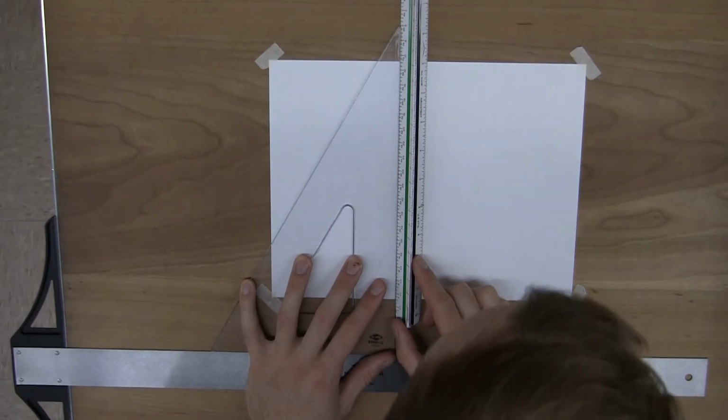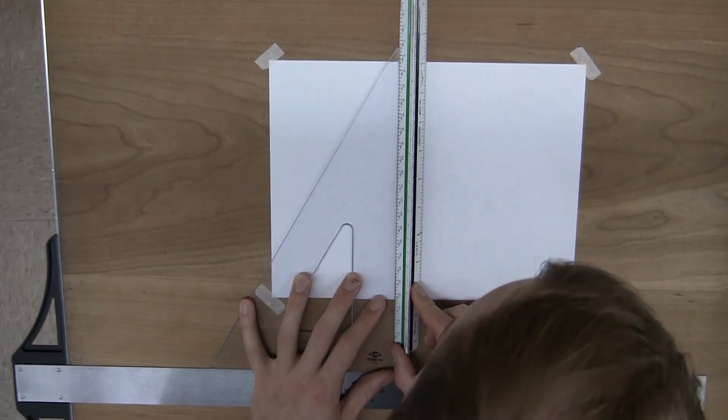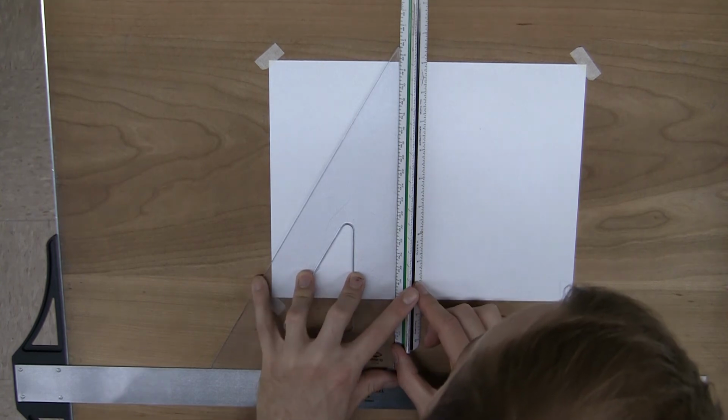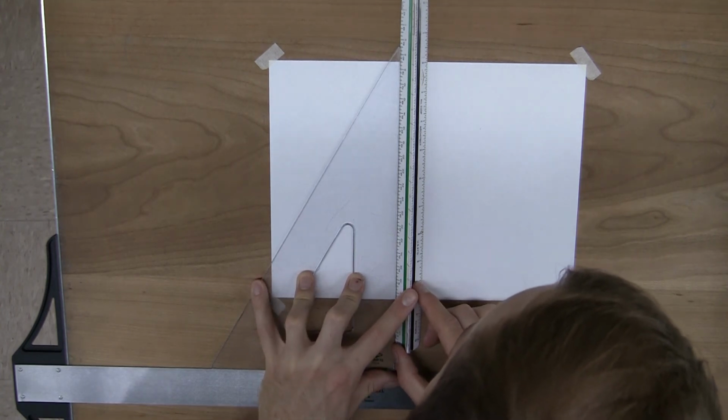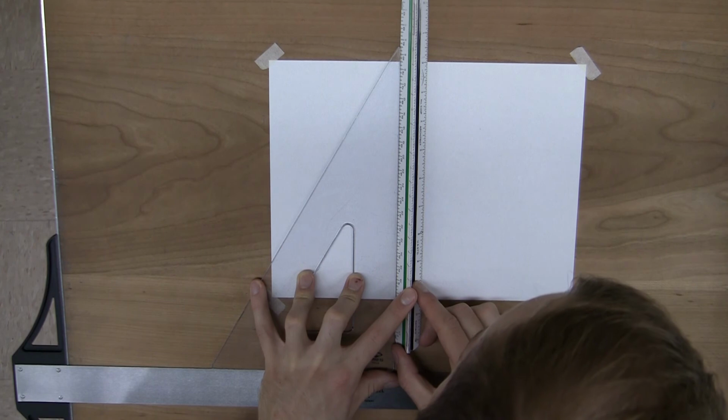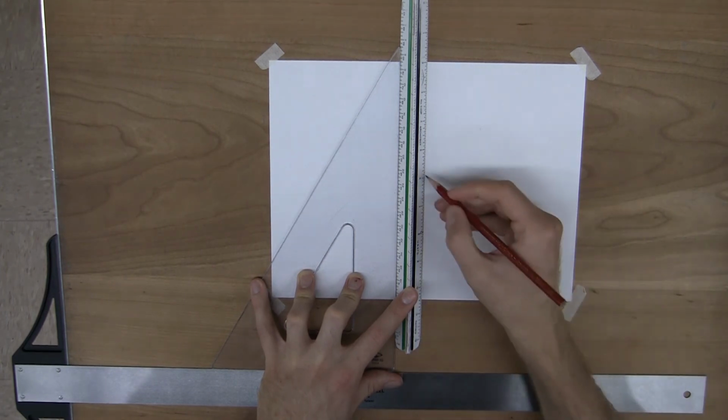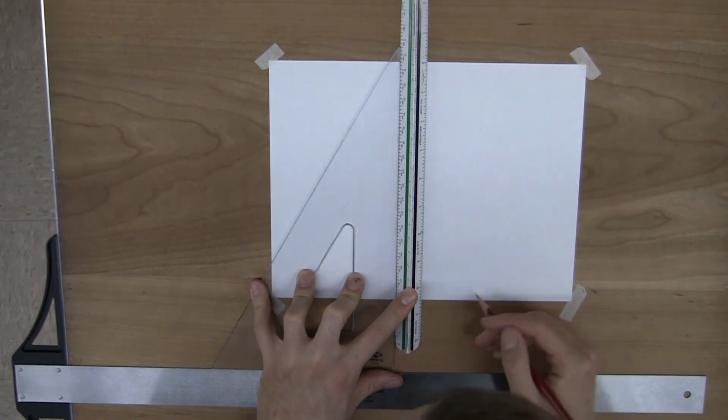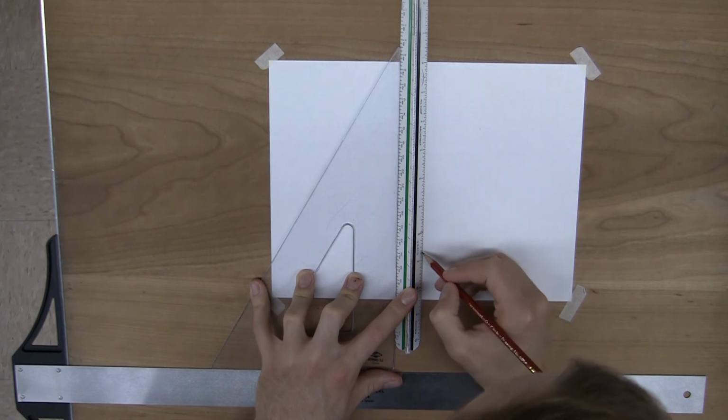How do I measure to a 32nd? This only goes to a 1/16 of an inch. Well, what I'm going to do is measure down 3 inches. So I'm starting at 6, I'm going to 9 just because of the way that my scale is oriented. 2, 3. And I could go down a 1/16. I know where 3 1/16 is, I know where 3 inches is. 3 1/32 is right in the middle.